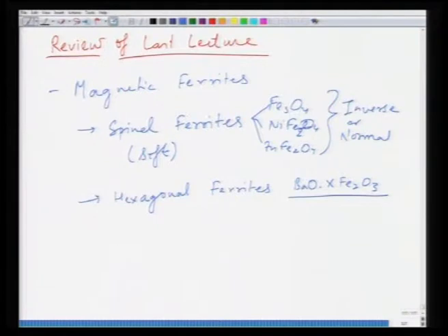and this x essentially happens to be 6, and this happens to have a mixing of FCC based and HCP based layers. Since FCC and HCP packing is fairly similar, except that in FCC you have ABC ABC and in HCP you have AB AB packing, they mix with each other quite well, resulting in a structure which is hexagonal in nature. And this material also has a large magnetization, as we discussed, based on the distribution of iron atoms, because iron here is the magnetic ion.